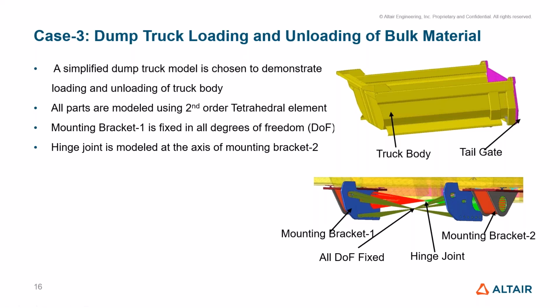We can still extend it, but the computational time will increase. Here the blue mounting bracket, which was connected to the whole structure, is constrained in all DOF, and for mounting bracket 2 you can see the red and green rigids, which were connected and created with a hinge joint to rotate when we apply a load over the truck body.